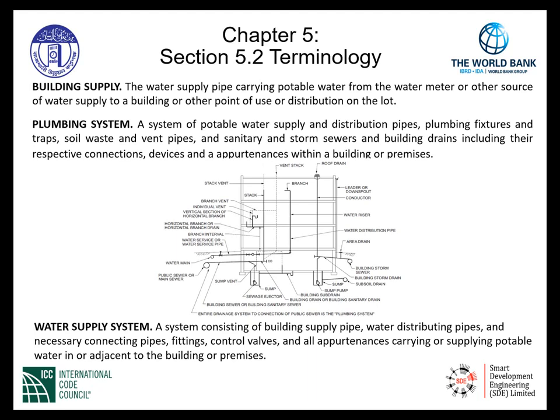As can be seen, we see where the water main is located outside of the building. It is labeled water main. From the water main, there is a tap off of the water main that supplies water through a pipe to a valve. This is usually a utility shutoff valve or a utility stop valve located at the street for a public water main.